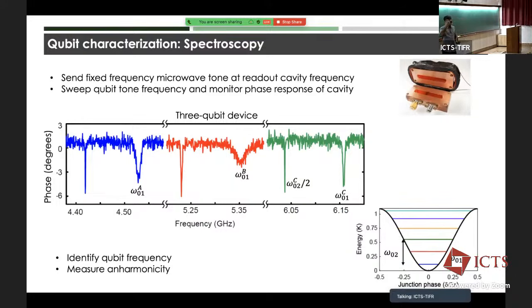So just looking at the plot, how do you know which frequency is which? Okay. That's because we have designed the qubits in a particular way. These frequencies are roughly 1 gigahertz apart, so your estimate is definitely accurate to that level. And for this particular 3-qubit device, we knew that there will be 3 lines. So once we know which is the lowest line and which is the middle line, which is the largest one, we know which qubits we are talking about.